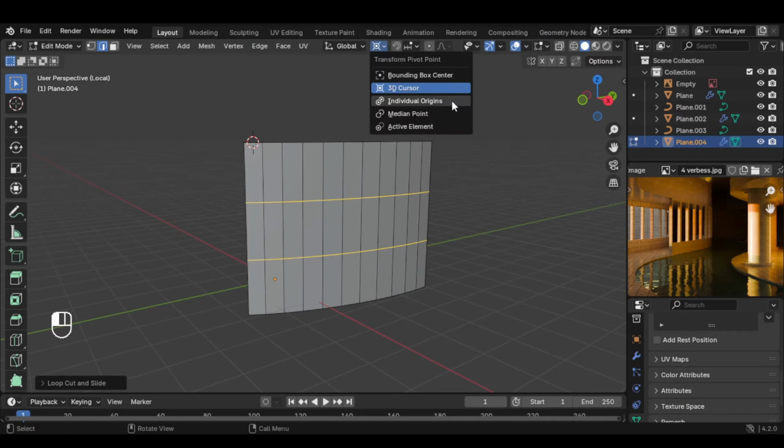And what you can do next is these windows here. So let's go back and select the building, go to edit mode, and let's make a couple of more loop cuts here by pressing Ctrl R and scroll up with your mouse wheel, and let's match it to the auto cuts. I think 5 should be good. Let's go to edit mode and let's press 3 and let's select these windows here by pressing C. To about here is fine.